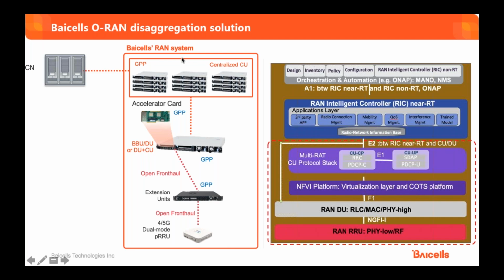And if you look at this graph or photo right here, the Pico radio unit is the RU functional split. Then it connects to the BBU, which can be the DU and CU functions together, or they can also be split. So this dotted line is a fronthaul, and then you have the backhaul from the BBU, or the baseband unit, all the way to the core network.